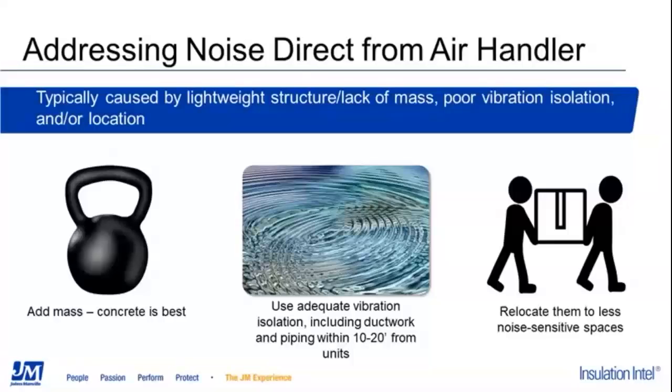And as the design allows, units should be placed near or over non-noise sensitive spaces. So you're removing that source, that noise path, so ideally those conference rooms that are on the top level are not being affected by these units. If there's still issues with direct noise and vibrations, a different unit may need to be selected.